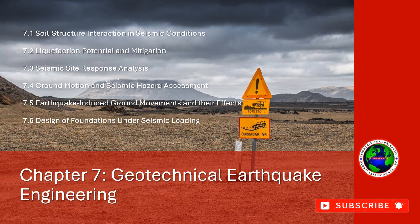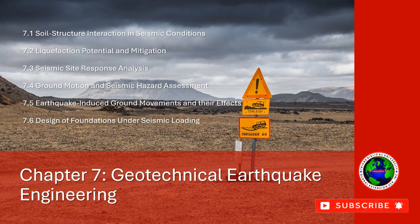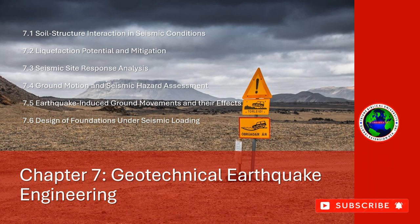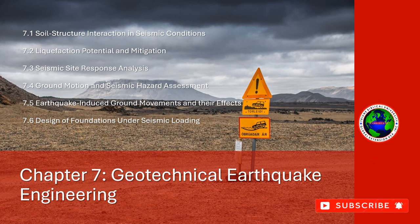Compaction grouting. This method involves injecting a grout mixture into the soil under pressure to densify loose, saturated sands and silts, improving the soil's resistance to liquefaction. Jet grouting. Jet grouting involves injecting a high-pressure jet of grout into the soil to create solidified columns that increase soil strength and reduce liquefaction potential.